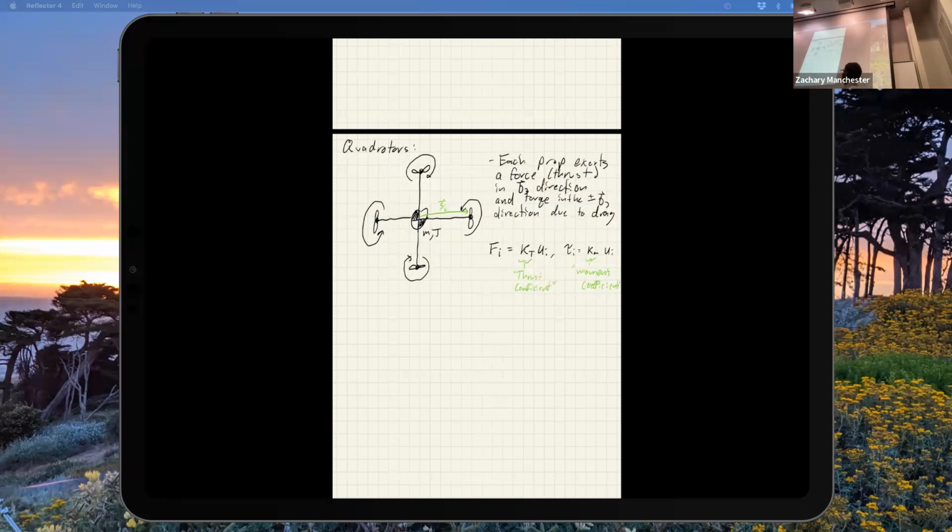In practice, this is really proportional to omega squared. So you would write that down, and then this would be a torque, and you'd have Newton-Euler dynamics for the props, and you'd account for airflow over the prop in the horizontal plane, right? Which is going to impact this, because if I'm moving this way and my prop's doing this, I've got more airflow over this side than the receding blade, right? This is actually what sets the speed limit for helicopters.